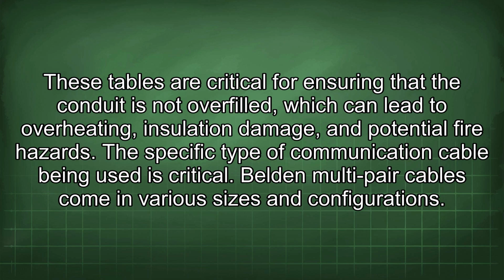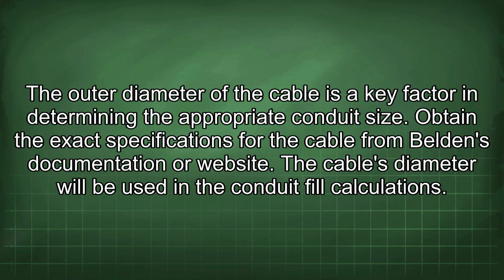Belden multi-pair cables come in various sizes and configurations. The outer diameter of the cable is a key factor in determining the appropriate conduit size. Obtain the exact specifications for the cable from Belden's documentation or website. The cable's diameter will be used in the conduit fill calculations.